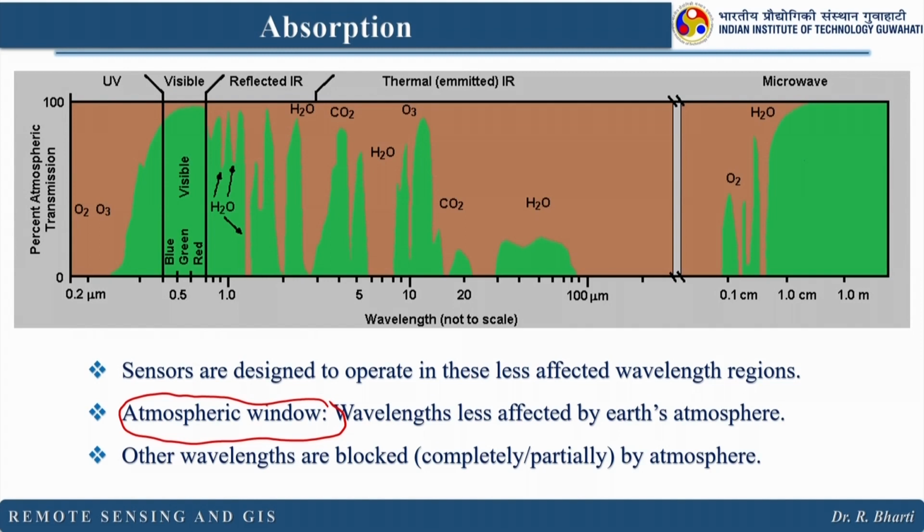Now, here there is very interesting information. There are a few wavelengths which were blocked earlier and are blocked now too, but in the beginning of remote sensing they were known as noise. If you have more interaction with the atmospheric constituents, you will have modified signals that you cannot use to really know what is lying on the surface in that particular wavelength region. So, we used to call them noise, but nowadays that noise is one type of data which can be used to identify the atmospheric constituents. If the constituent is more, you will have more interaction and more noise. So, now we are resolving it in terms of information. Slowly we are evolving and moving ahead in a different direction.